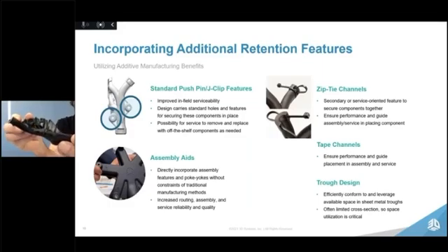The geometry of the retainer itself is a great example of the design freedom and ability to conform to tight spaces and provide better packaging reliability and functionality. This part had to fit within a particular corner on some of the pressed metal surfaces within the door assembly, and distribute elements of the harness accurately within the space. So if you see the geometry of the part here, you'll see some routing for the harness itself down each of the individual channels. This then distributes the elements of the harness into the right spaces. The geometry of the part itself, you'll see, is essentially a 90-degree right angle fitting into the corner of a door skin or a door assembly.